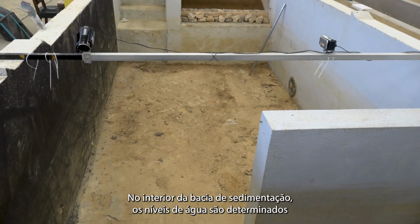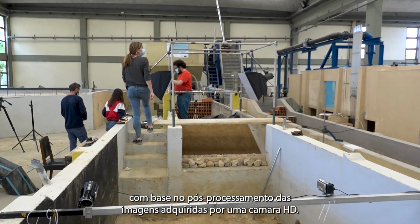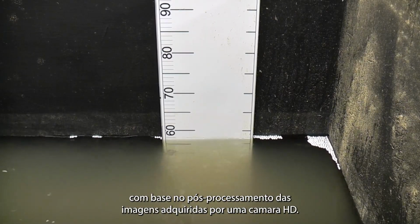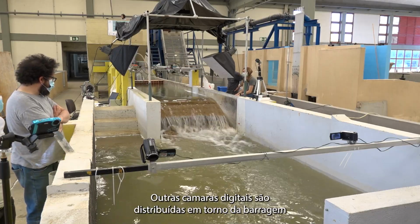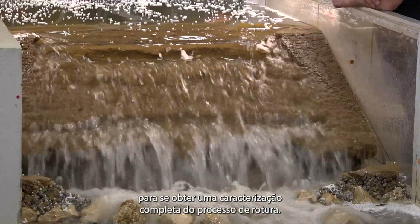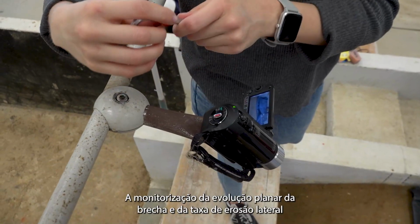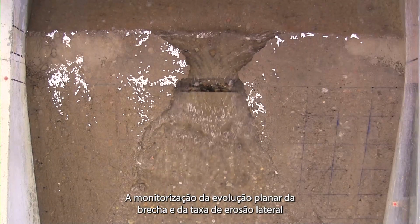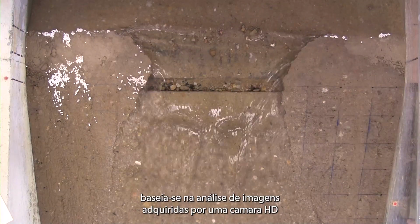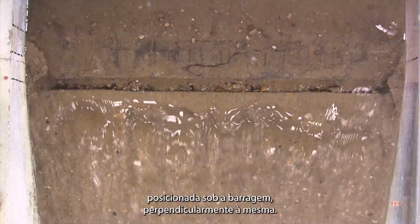Inside the settling basin, water levels are determined by processing the footage of an HD camera. Other digital cameras are placed around the dam to obtain a complete characterization of the failure process. An HD camera was placed above the dam to monitor the breach evolution from the top, allowing for determining the lateral erosion rate.